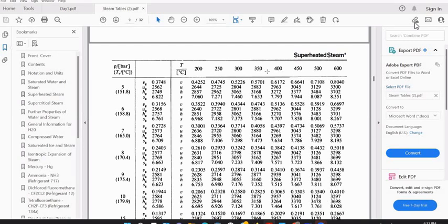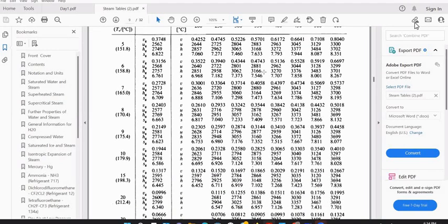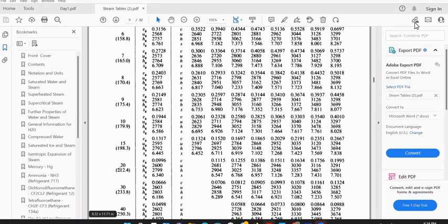But you can see in between, you have the temperature 350 and then 400. 20 bar is here. But thing is, you don't have 360. Temperature 360 you don't have. Then you have to go for the interpolation. Mathematical interpolation, because here 20 bar, now values are here anyway.